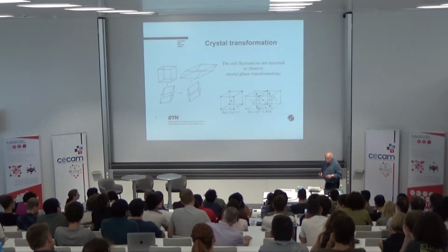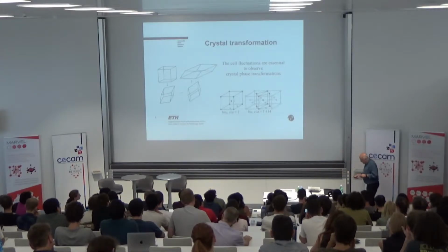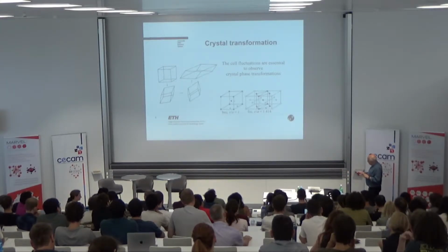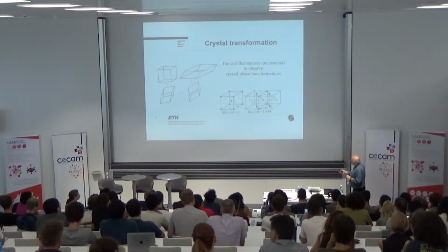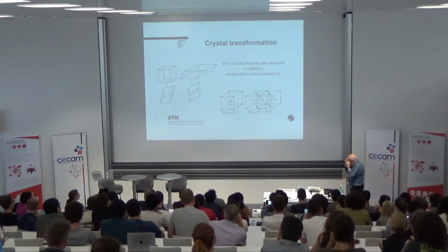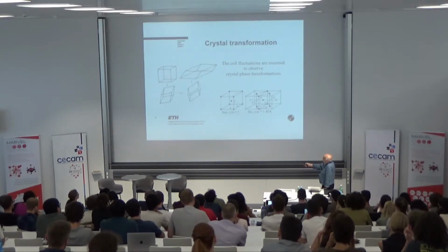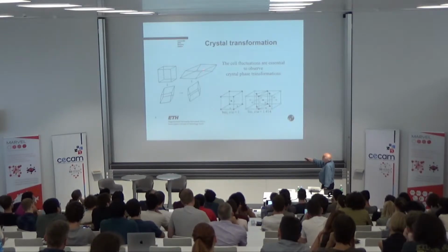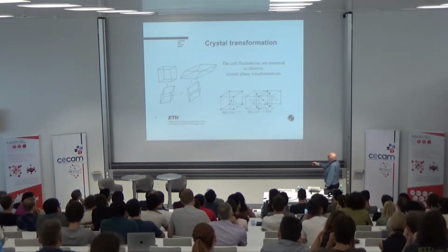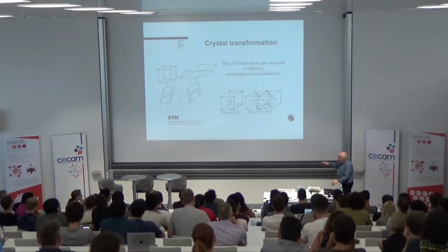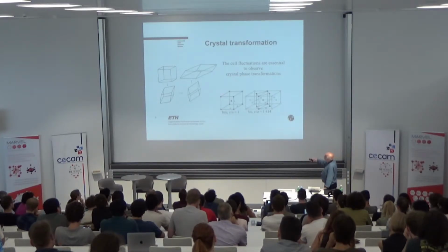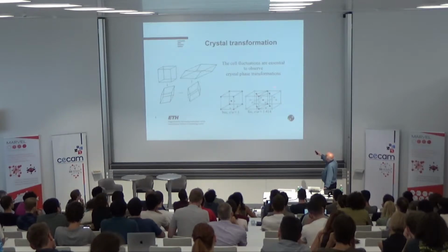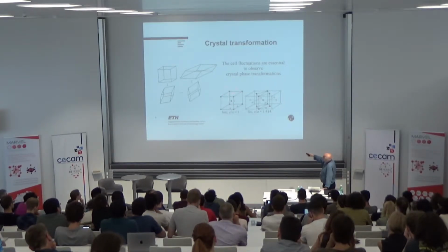And so the idea came at the time that, rather than using a cubic cell, in the spirit of Hans Christian Andersen, we allow the cell to vary in shape. This can indeed allow going from one crystal structure to the other. This is what is called the Bain transformation. See, this is a BCC.